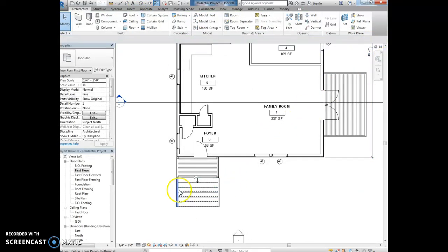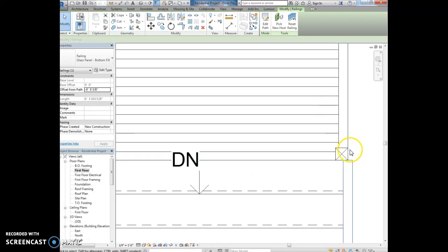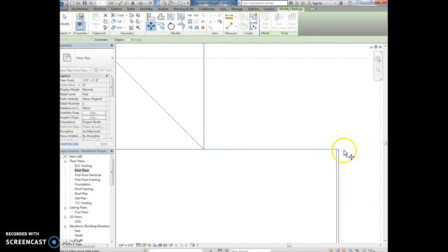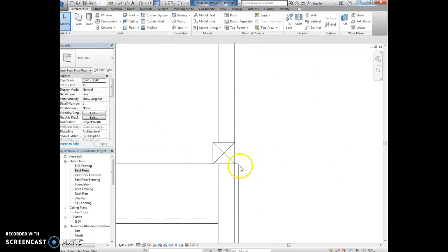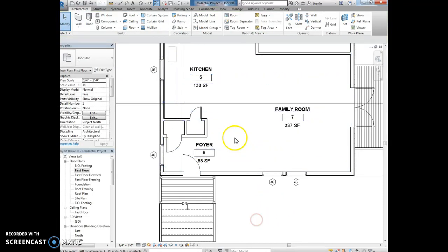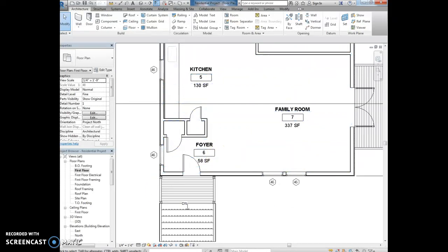Okay, so then last thing we're going to do is clean up our drawing. So we're going to move this railing. If this happened to you, make sure that you move it so that it aligns properly with the posts, because mine was not. And then we need to add a floor to the inside of our building. So just take note of which direction the floor joists are spanning, so they're running horizontal right now.